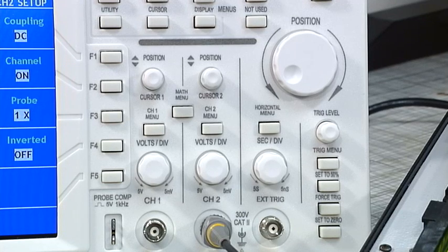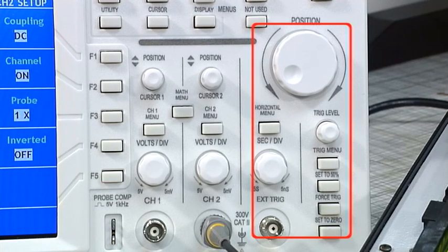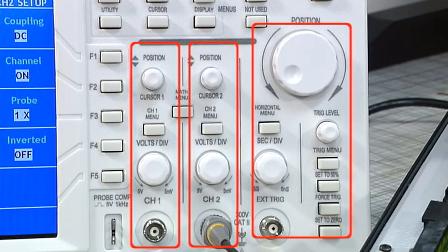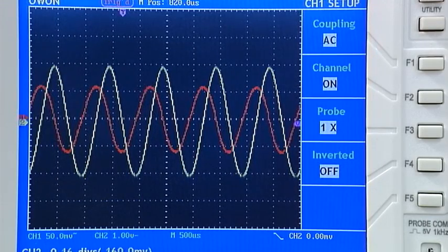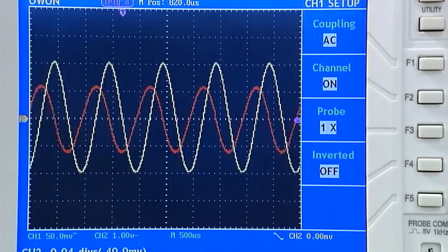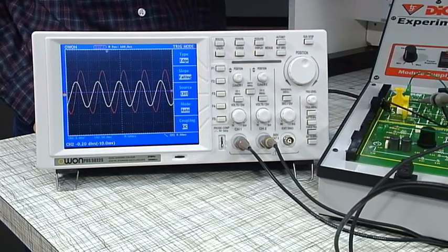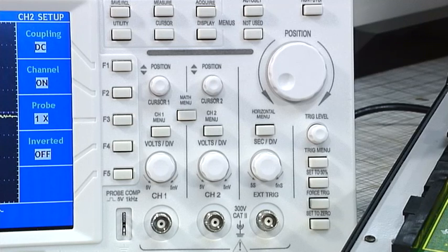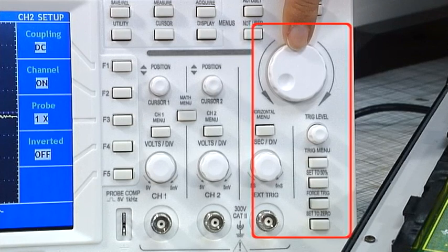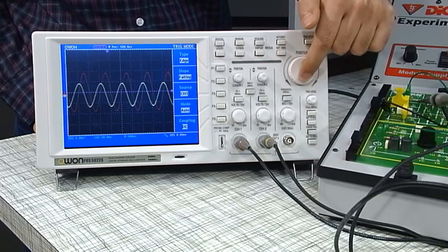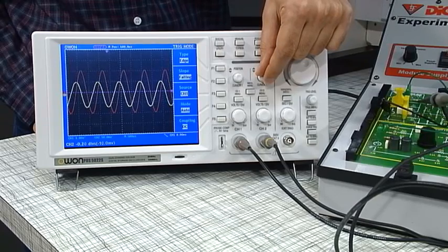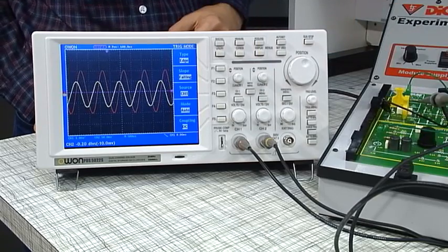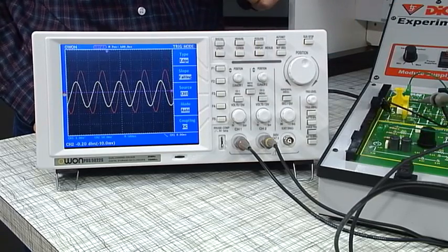The two main sets of controls are for the time base and Y amplifier settings. Most oscilloscopes can display two traces at any one time using two channels, and each channel has its own set of Y amplifier controls. The time-base controls are common to both Y amplifier channels. It is important to note that adjusting the front panel controls does not change the measurement. It only affects the trace on the screen in a way that ensures a convenient display.